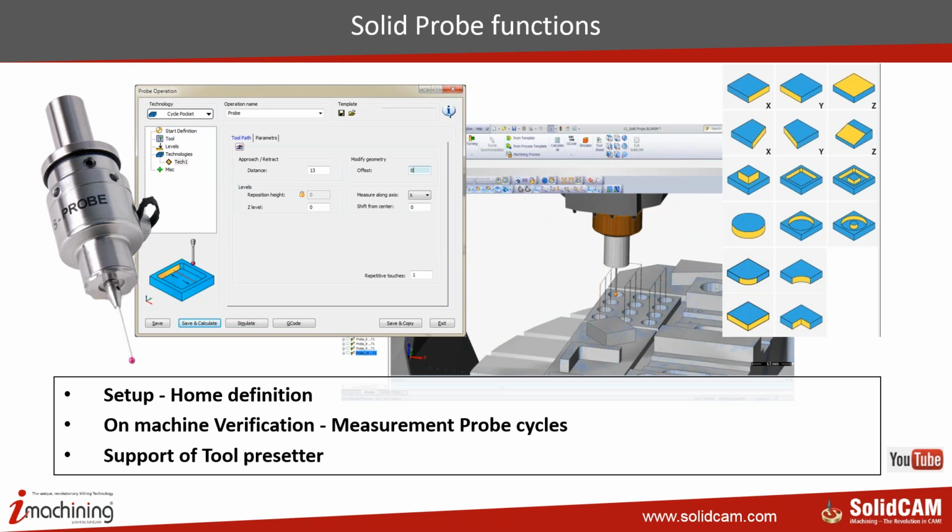However, today when people use a probe, they use it manually. What do I mean by manually? They'll go with the probe to the machine itself, and they'll feed it in slowly, step by step, to get one edge, and then get another edge, and then get the Z level, and put those values in to get your home position. This is one of the things we can do inside SolidCAM, which will eliminate the need for going up to the machine and physically doing it.